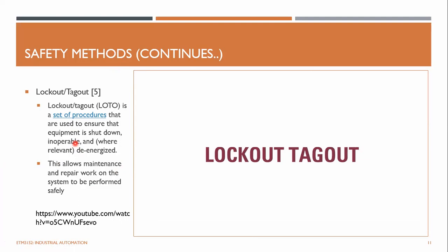So you have to use this kind of lockout tagout: you turn off the DOL and put a lock so no one can come and operate it until your work is done, right? So this video will show that kind of example. Let's take a look.